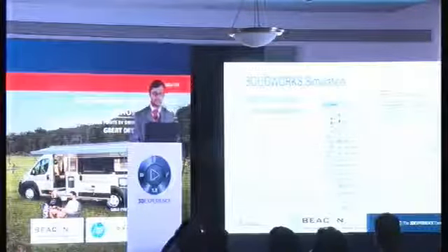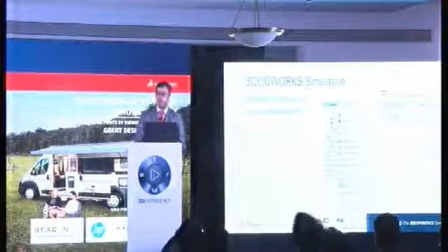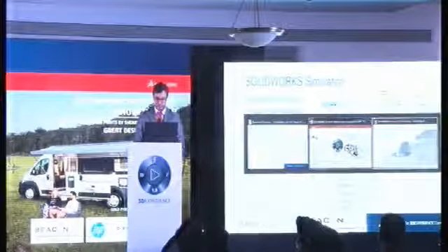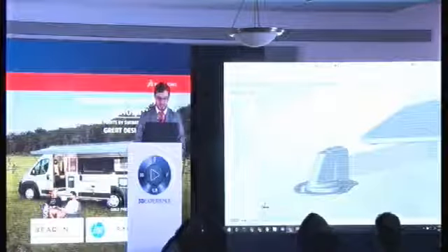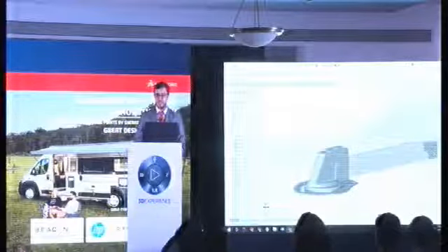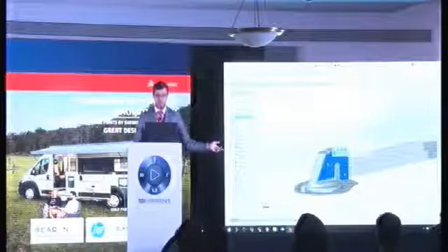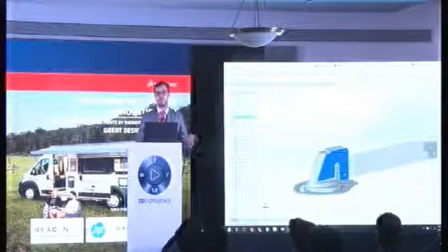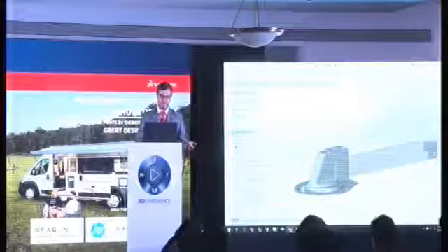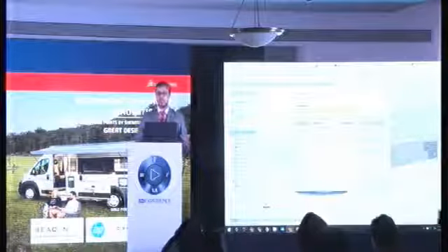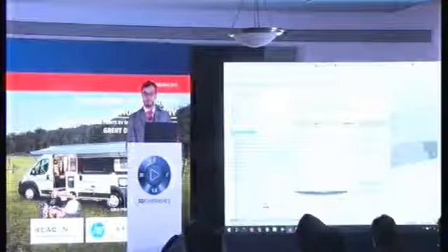So the next feature is import study feature. Now you can import the study features directly from the part and assembly level. Let me just show you what it means. So if I go to this TV antenna assembly over here, I already have a study. Now this whole assembly requires certain fixtures or boundary conditions. Now this part over here which we saw earlier already contains such fixtures or boundary conditions. I can go ahead and import study features directly from the part or sub-assembly level. So this saves you a lot of time for defining the boundary conditions again and again.